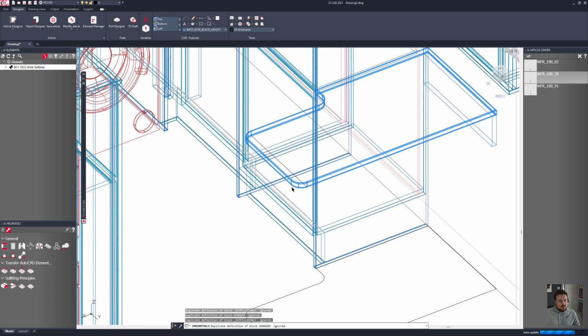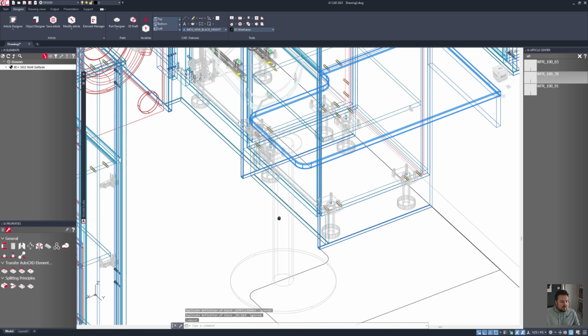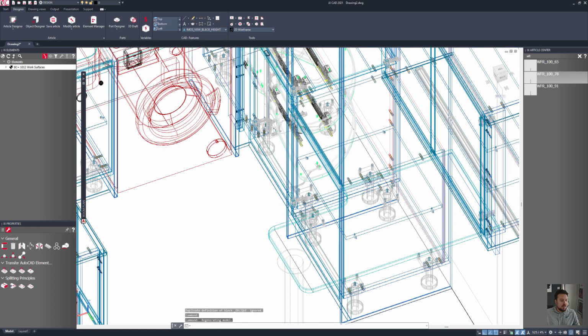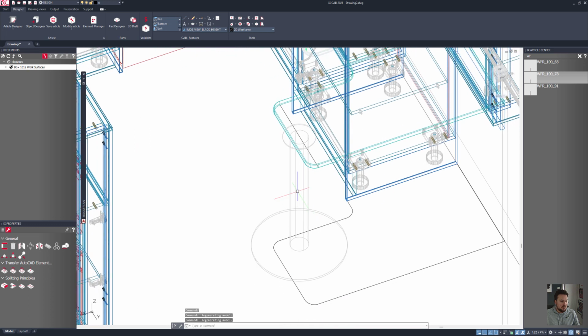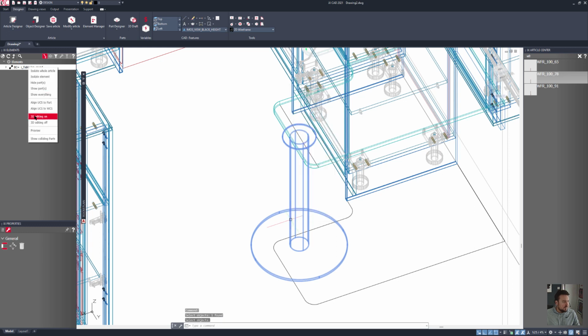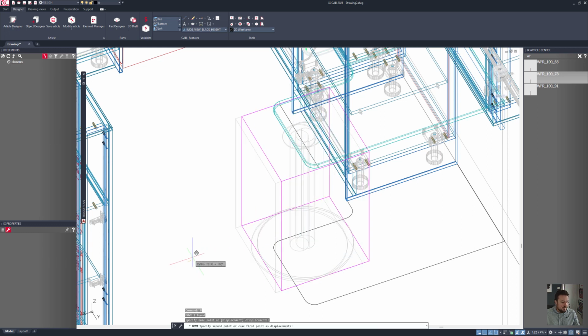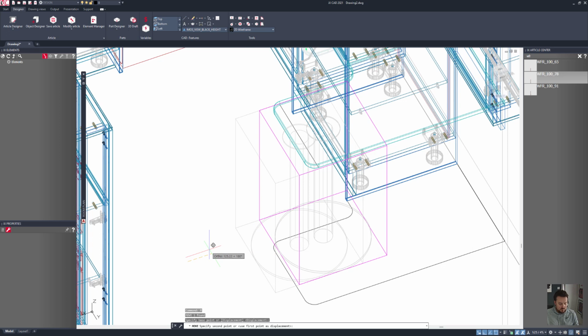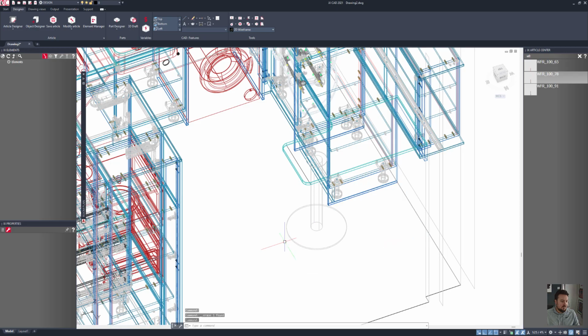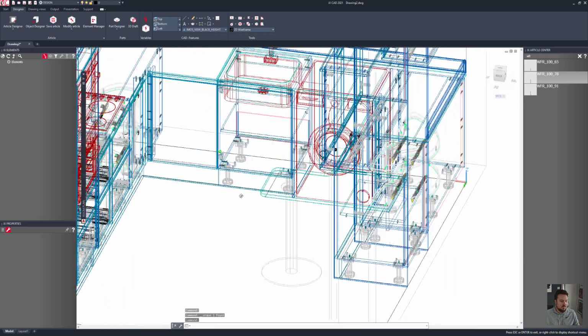Okay, so the system's now going to refresh. It's going to add in all of my fittings and hardware. Hopefully you'll see in here I've got my table leg that's been brought through just to support this. I need to nudge that along a little bit, I think. So what I'll do is select that part and turn 3D working on. I can then grab it and move it over using AutoCAD Move 150 millimeters and then turn 3D editing off. I'll get rid of my polyline in there as well.